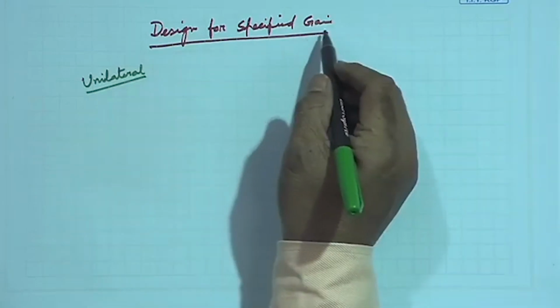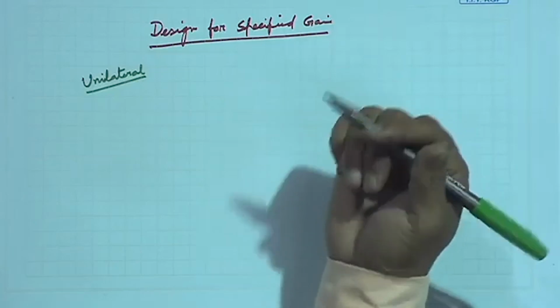When we design for a specified gain which is less than the maximum transducer gain possible, we are deliberately putting some mismatch in. We are not properly conjugate matching, and that is why we get less gain, but we are satisfied with that, because we can sometimes suffer that much mismatch and power loss. If not, then do the conjugate matching, which is the best design.